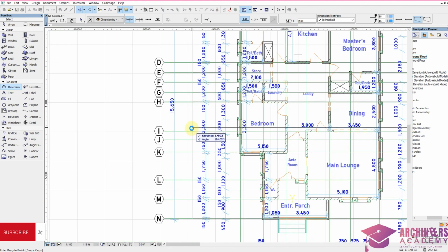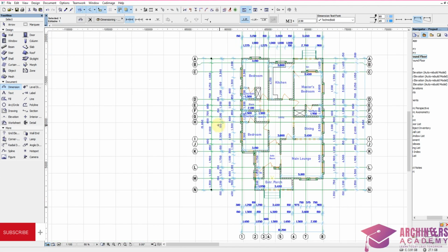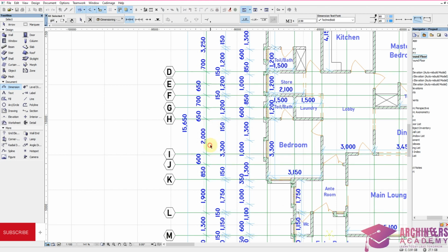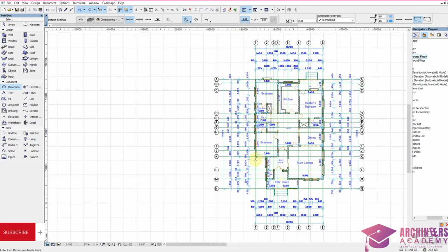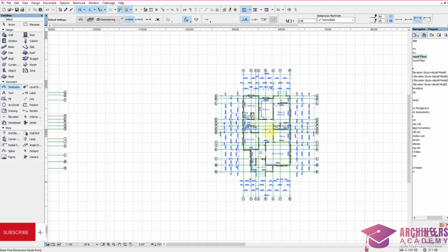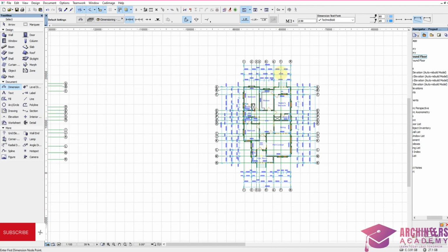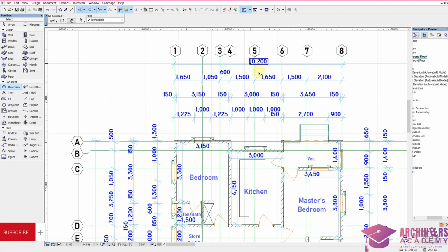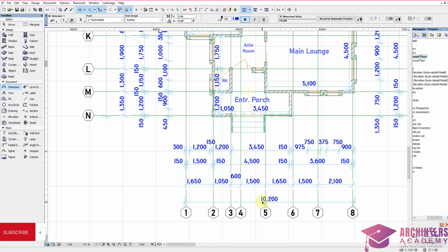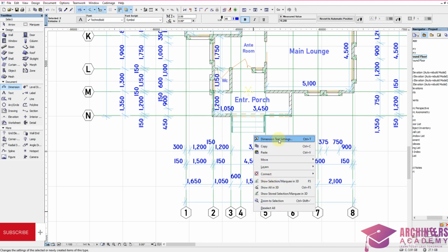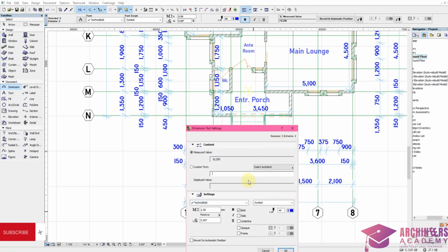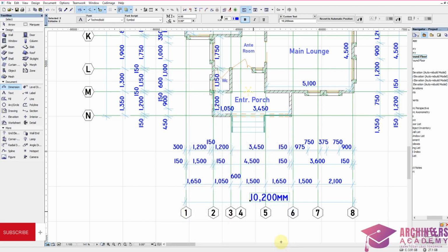As you can see right now, I'm almost done with my working drawings. So this is how a full working drawing should be. Not only having your internal dimensioning, but also your external dimensioning. You can add more graphics to your design by making the total length much bigger or bolder. You can see what I did. I highlighted it and right clicked, then changed this to 2000, then added mm in small letters, then made it 4. You can do this to add more graphics to your work.